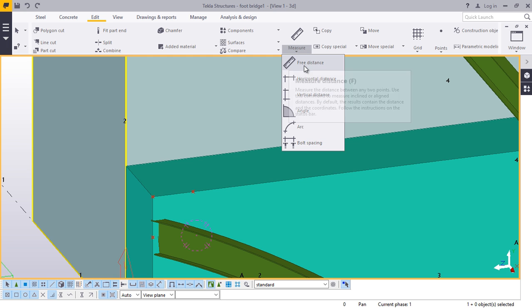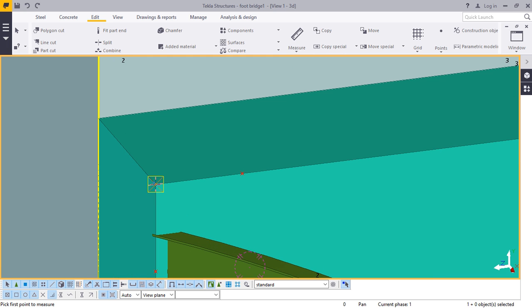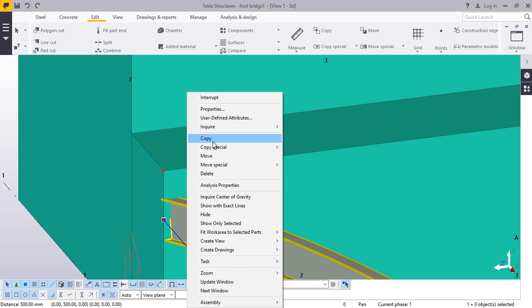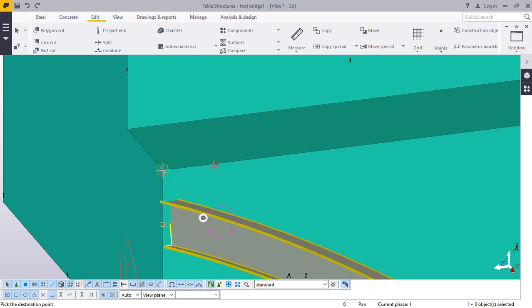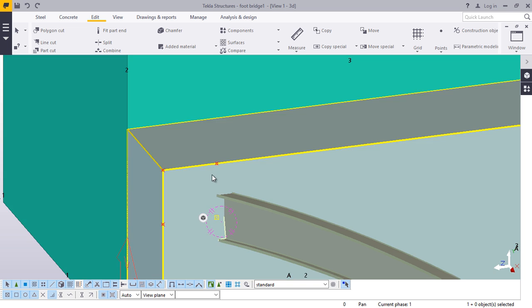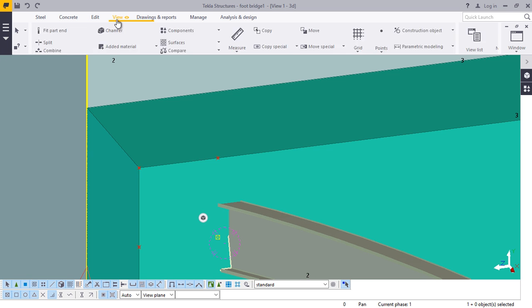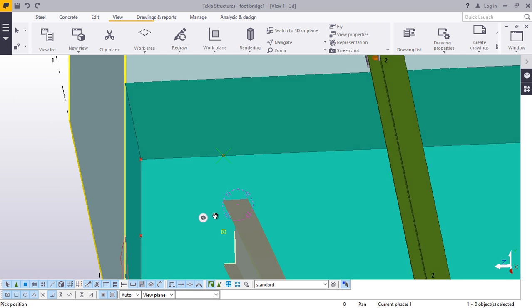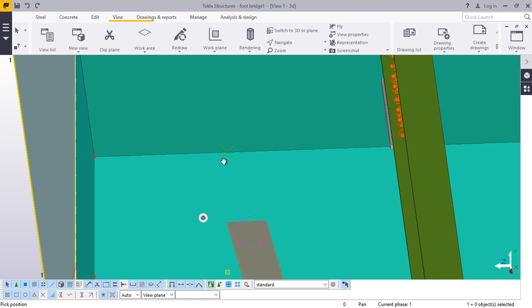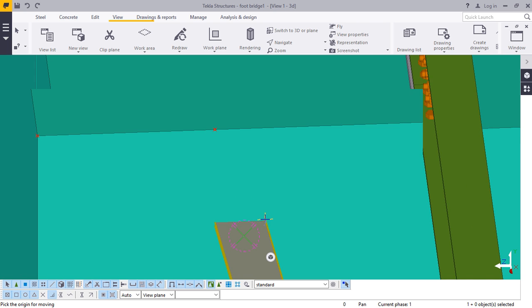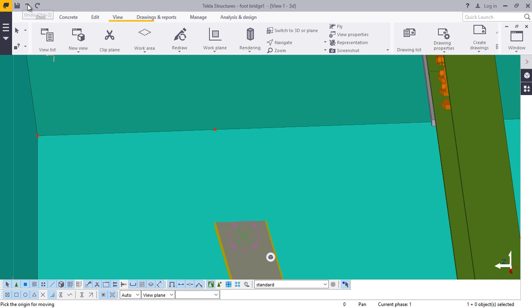or prior to doing that, let's check this distances. To that is 500. Click this, right click, click move from here 500 and enter that. Click view, navigate, rotate with mouse, turn this round. Click this, right click, move, and do that.